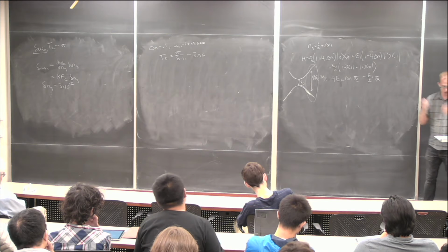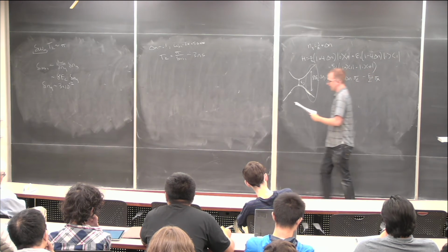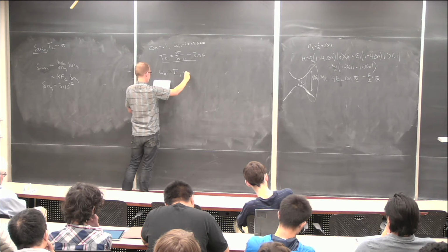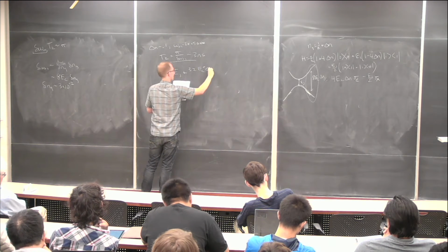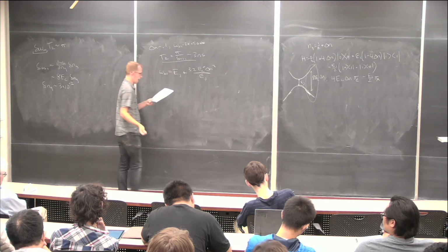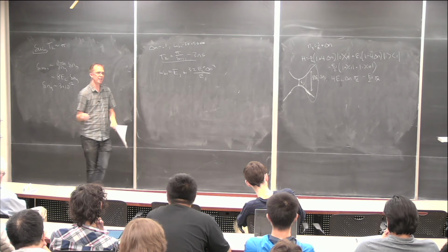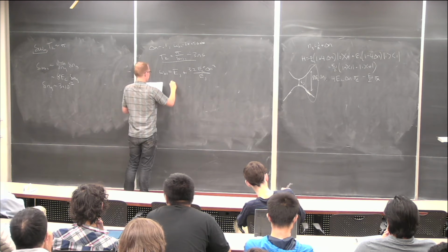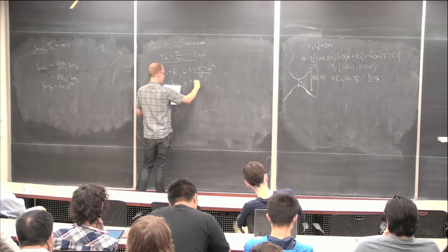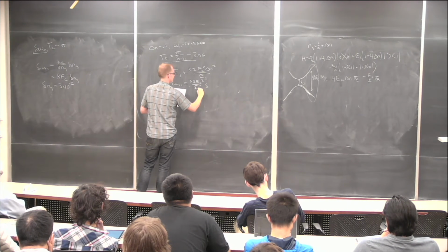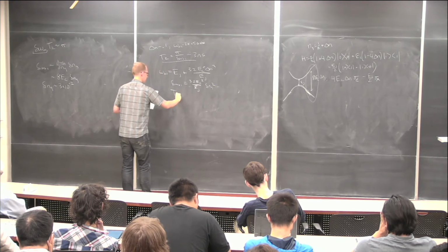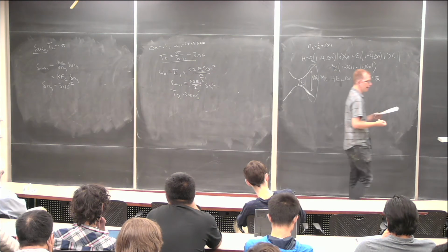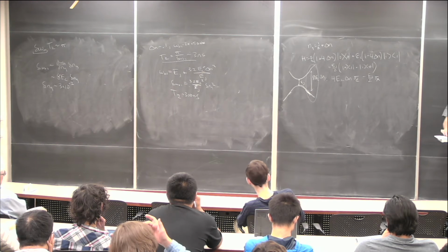And so you can do a second order expansion, and at this point, omega 01 is EJ plus 32 EC squared delta n squared over EJ. You can again approximate delta omega 01, except now it's second order dependent on your excursions in Ng. And that says delta omega 01 winds up being 32 EC squared over EJ times delta Ng squared, which gives you a T2 of approximately 300 nanoseconds. So we got 2 orders of magnitude better by choosing an appropriate bias condition.